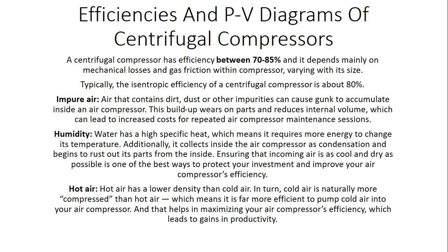Hot air. Hot air has a lower density than cold air. In turn, cold air is naturally more compressed than hot air, which means it is far more efficient to pump cold air into your air compressor than hot air. Yeah, that is very understandable by itself. You can maximize your air compressor efficiency by ensuring that it is cold air that is taken in rather than hot air.